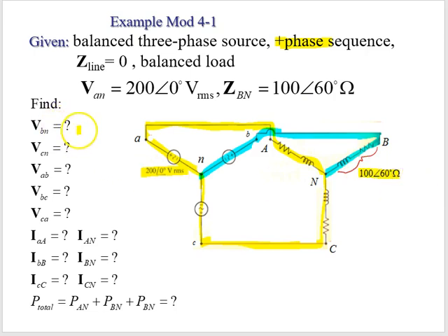And then we state what we want to find in terms of the phasor voltages, the capital bold font, and we're using our double script notation, where the first two are the other phase voltages. Here are our three line voltages. And then here are our currents. We have a line current IAA, and then we additionally have this phase current IAN. Finding those, it asks to find the total power. Total power is the average power, so that total power is the power absorbed in each of these three phases: